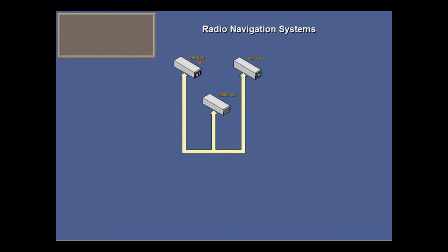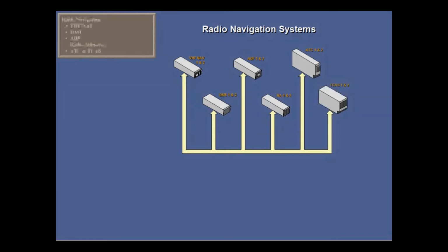In this lesson, we'll briefly cover the components of the radio navigation systems, including the VHF Nav System for VOR and ILS navigation, the distance measuring equipment DME system, the automatic direction finding ADF system, the radio altimeter system, the air traffic control transponder system, and TCAS. But the radio management system, VHF COM, and associated voice and data communication systems are covered in Module 16.